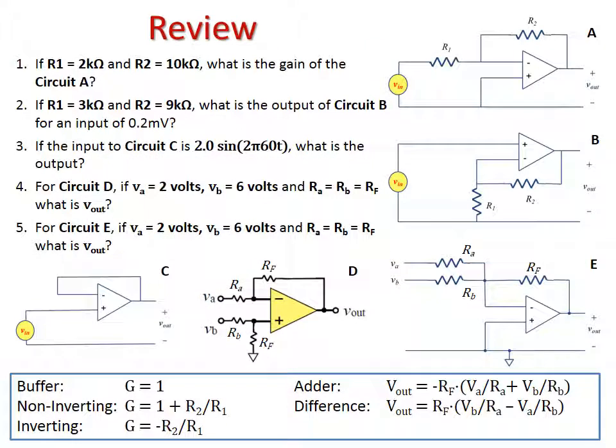So finally, we're going to review this, and we've used this slide a couple of times now, but complete this slide on your own. See if you got it correct, if you've identified the correct op amps. That's the first step. And then if you identified the correct op amps, that you have created the correct gains for them. So one other thing I'll notice in this one, in the inverting slide, that should be gain equals minus R2 divided by R1. There's a negative sign in there. Just making sure that it's there. So pause now and solve.